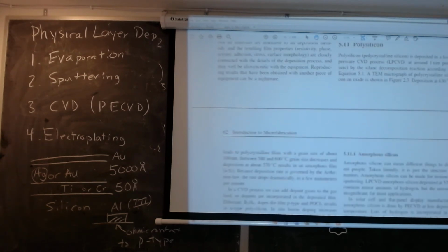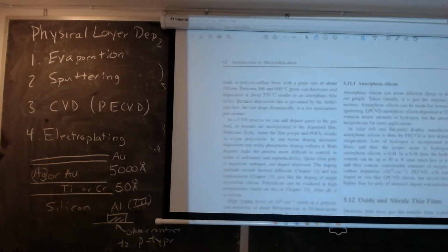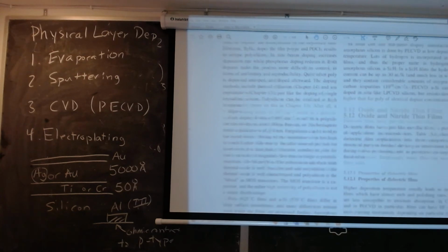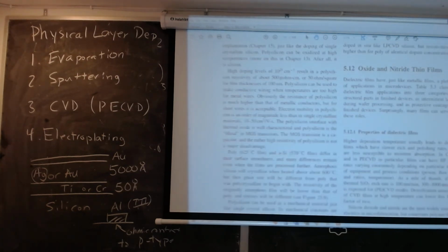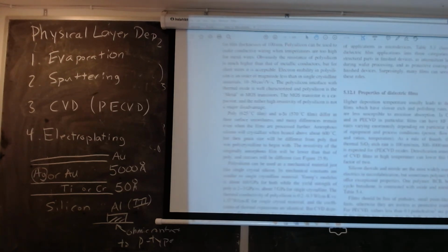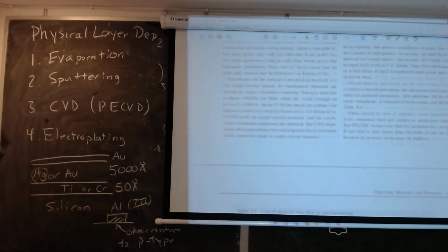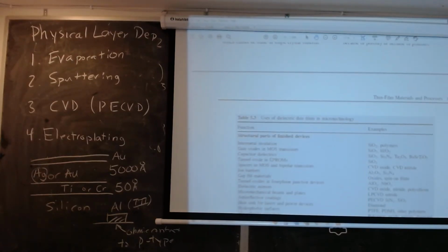All right, then other thin films, polysilicon is typically used. Now, CVD tends to give you polysilicon, which means it's crystalline with different grains. You can get amorphous silicon, which is purely amorphous like glass, and it's useful for some applications. But the usual dielectrics you're interested in are oxides and nitrides. We've talked about PECVD versus LPCVD, and the fact that with silicon nitride under PECVD, you can adjust the ratio of silicon to nitrogen.